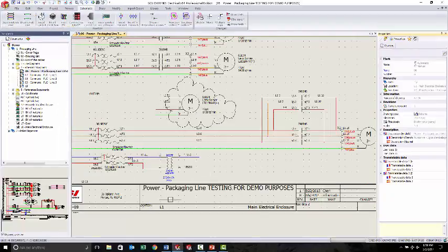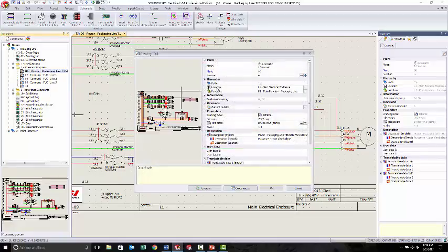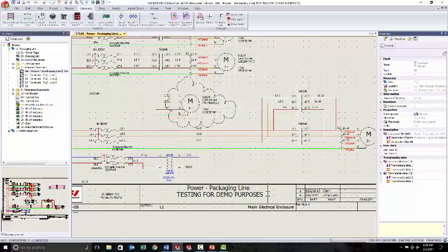Now that title block is going to be updated by simply highlighting the update title block. Say yes. Now this has not changed because I now need to use something called a pipe symbol. So in my properties here where I want the line break, I would come over here and add the pipe symbol, being the symbol that is the straight up and down line. And I say okay. And it breaks it up into 2 lines. Now, this works great, except that in 2016, when you came to the reports, the report all of a sudden still showed the pipe symbol.